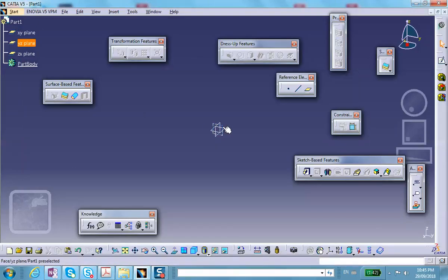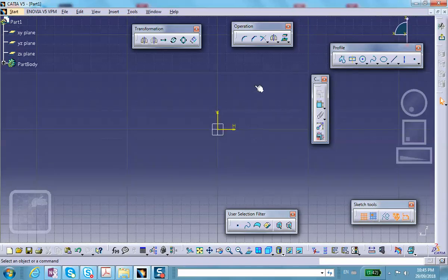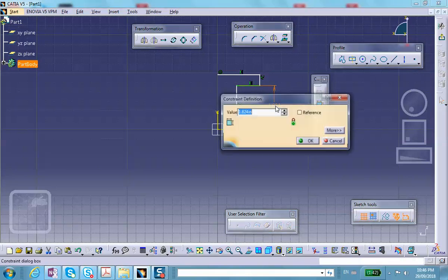On a convenient plane, on this vertical plane, I will draw that I-beam that I want with the dimensions. However, I'm going to draw it symmetrically so that later on I can cut it to model it also using planes of symmetry. So let me make something like that. Dimension these things. So this is half an inch, 0.5.